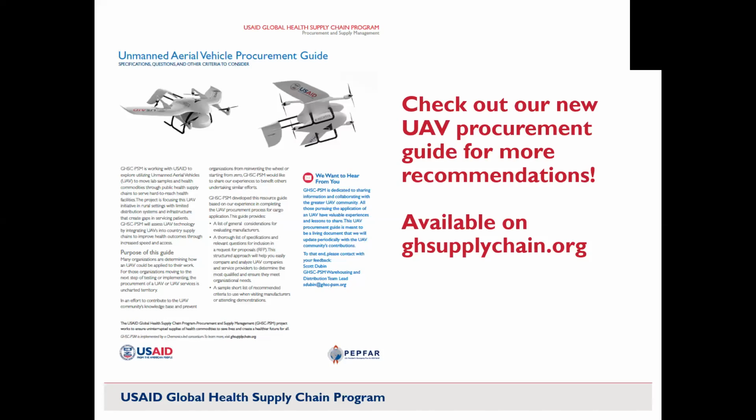And so I think one thing to keep in mind regarding temperature sensitive items is that the flight time is often not very long for a UAV to get to a location. So if it's flying at 80 kilometers an hour, you're likely going to be reaching a facility in less than an hour. And so what we expect to do is to have insulation inside the cargo area. So that would allow us to move temperature sensitive products. So both temperature monitoring to occur inside so we can have certainty, but no need for refrigeration itself.